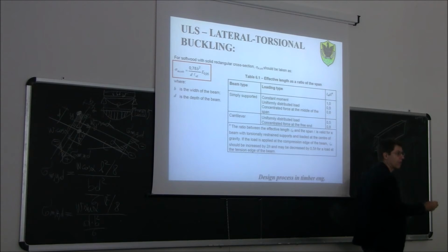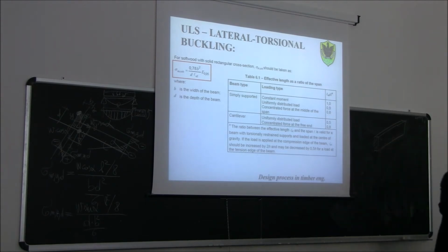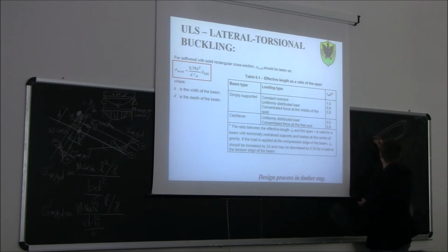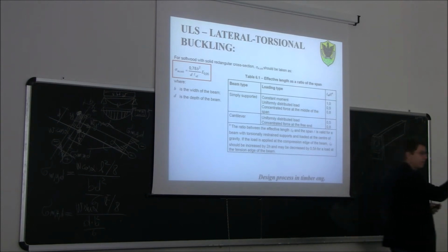Okay? So the classical kind of torsional restraint that we study in a mechanical structure is a kind of fork. A fork like this, of course this is an approximation, just at the end of the beam, which is preventing this beam from rotating torsionally.